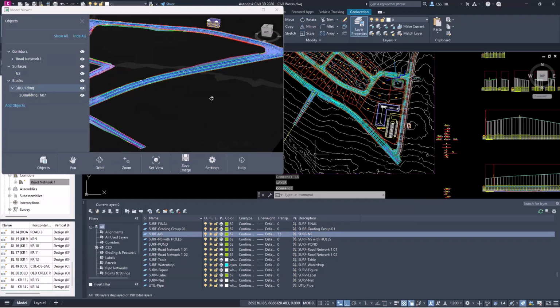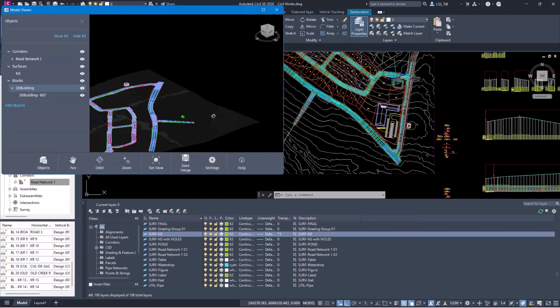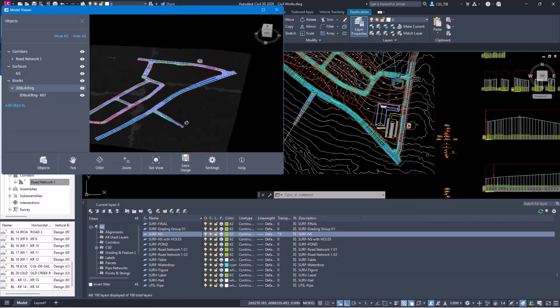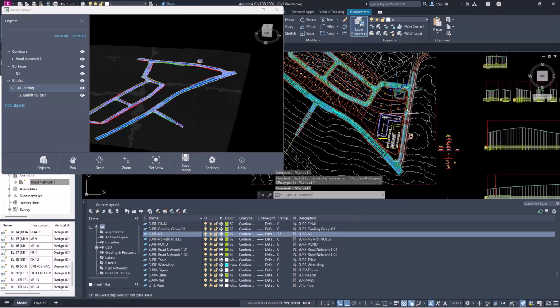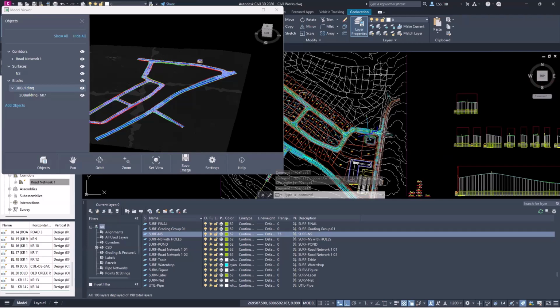that actually applies through to the triangles that are showing up in the 3D view. So you can actually set the transparency on things if you want. You can also just turn on and off the layer itself. So if I turn the layer off, the whole thing disappears from here in the drawing as well as in the model view. Another thing you can do is to show your line weights through. So if you've got objects with line weights turned on, so if I turn a couple of objects in here, I've got a few things set up to do this.